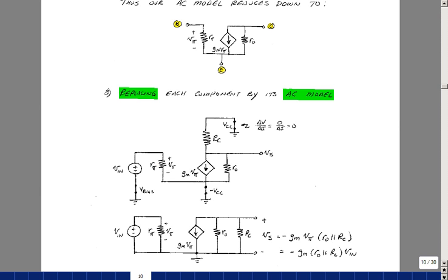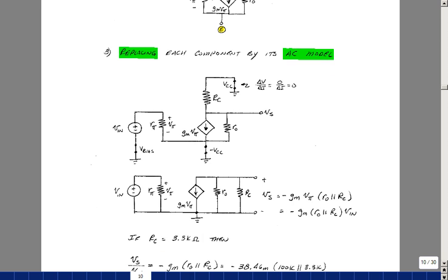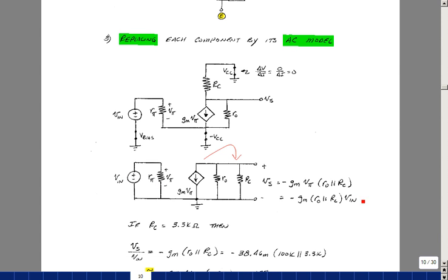Okay, with all the short circuits, now let's just redraw this. This is all shorted, so we're just along here, and then R_C folds over and it's in parallel with r0. So just symbolically then, the gain from here to here, and we'll label this as V_S, this is going to be feeding our power amplifier. So we're going to have all this current flowing into this parallel combination. So gm vπ times r0 in parallel with R_C. And vπ actually is Vn. So just replace the vπ by Vn.